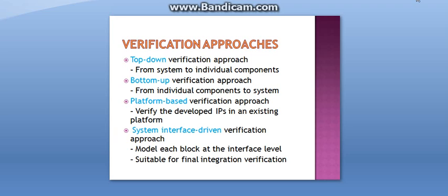Fourth is system interface driven SoC verification. It models each block at interface level. Besides the design under test, all others are interface models. It is suitable for final integration and verification.